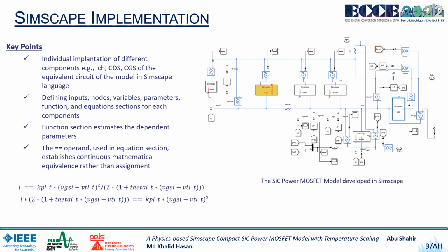The parameters denote fixed values which can be accessible even after developing the model component, while variables can change their value during each time step of the MATLAB simulation. The function section calculates the parameters which depend upon other parameters.